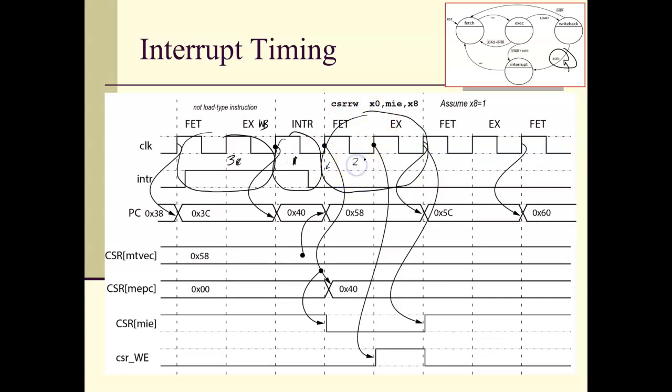First instruction in the interrupt service routine, that is 2 more clock cycles, and now my interrupts are enabled, so I'd better have that pulse gone by the end of this cycle right here, which is essentially going to be 2 more clock cycles. So you just don't want it longer than 8.